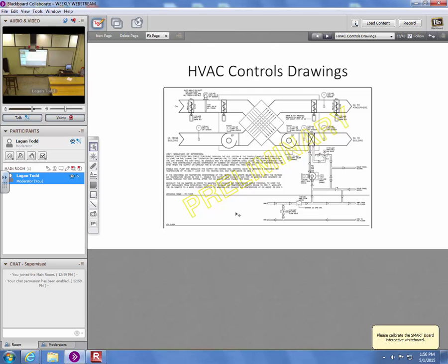You might see it doing something that just doesn't make sense to you, and it doesn't seem like it's doing what the last system of that type was doing that you looked at, and you could easily jump to the conclusion that therefore this is wrong, but you don't always know. I mean, it could be that the engineers knew something that was particularly unique about this system, and that it was very intentional. So if you can go back to these written sequences and controls drawings, you get a better idea of what was intended originally. And then you still might say, well, that's not the best sequence, and at least you're more educated in making that assessment.